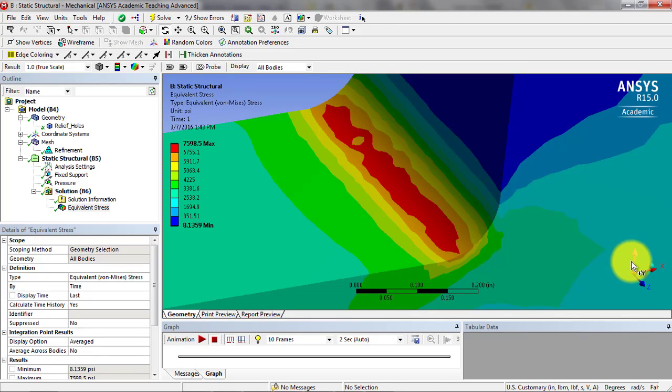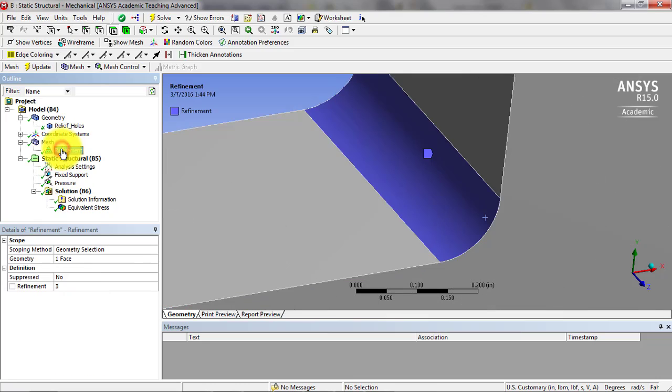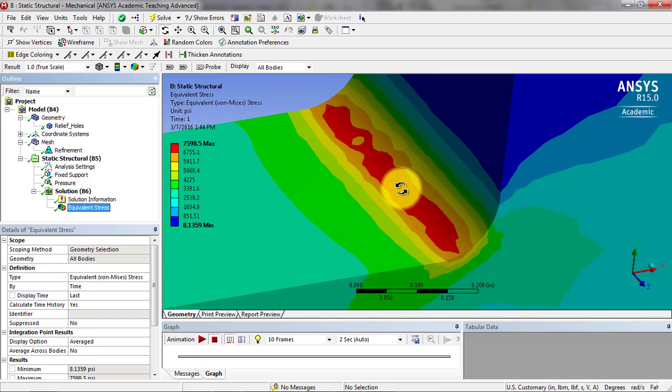And so now we still got a bunch of big red spots, but let's see where that's located. Let's see what the mesh looks like underneath it. And there's a bunch of nodes right in here. So again, it's still averaging in between nodes, but it's almost brought those two lines that we had before into being much more one stress concentration right in the middle there. Let's see what happens at the bottom.